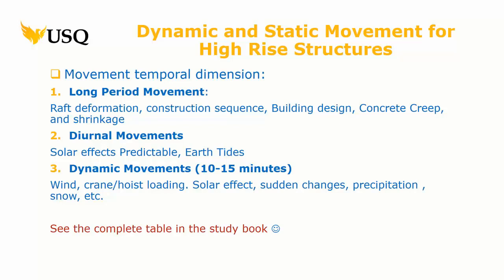Now, steel towers, we saw some before. Steel towers are a thing that people look at and go, oh, it's just a tall tower. But because it's steel, and the expansion rate of steel is greater than concrete, and greater than timber, and other factors, right? Steel towers can move a lot with the sun on them, right? So what they try to do is make sure that all of it is heating up at the same time. Therefore, the movement is directly up or directly down as it cools. Right, the raft itself at the bottom, any deformation in the raft tends to be in the middle, that's where most of the weight is.